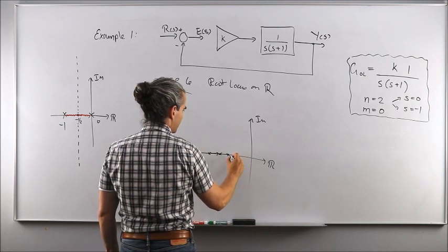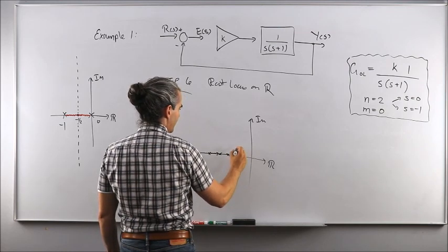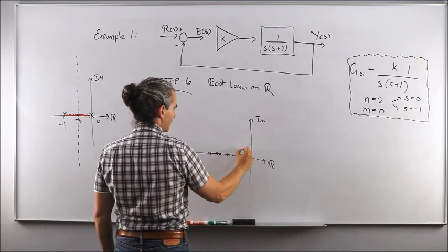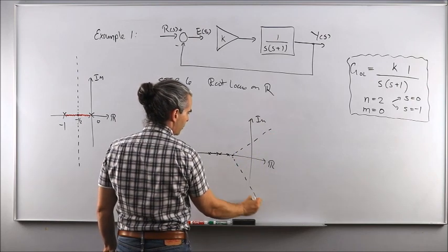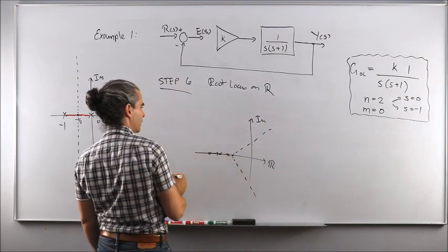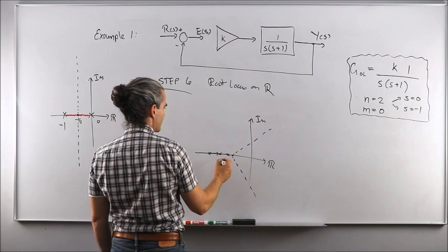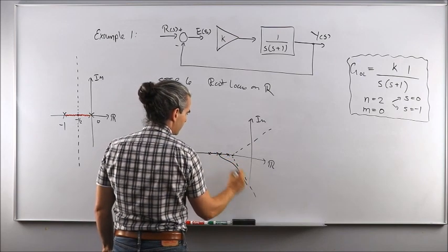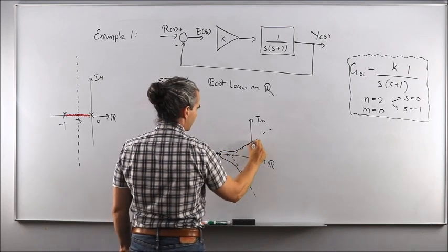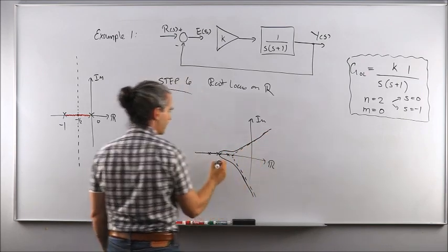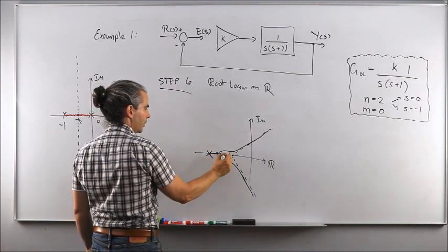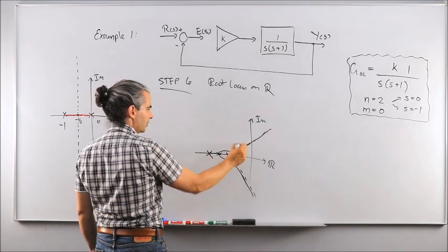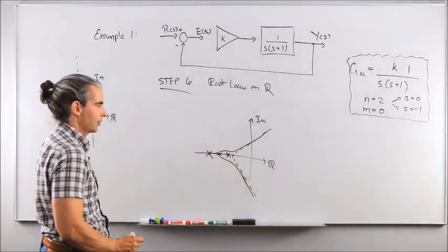So let's pretend that the intersection point of the asymptotes is here, further to the right of this pole. And that's an asymptote, another one, and obviously we need a third one. Maybe both poles would do a complex maneuver like that and end up following the asymptotes, yet the breakaway point of those two poles, being in between them, would be different than the intersection of the asymptotes. That can very well happen.